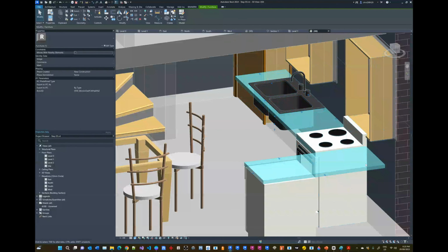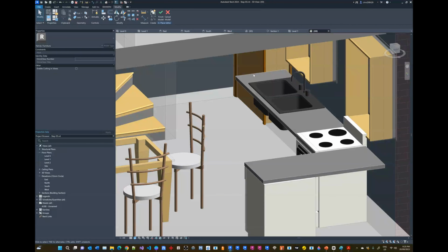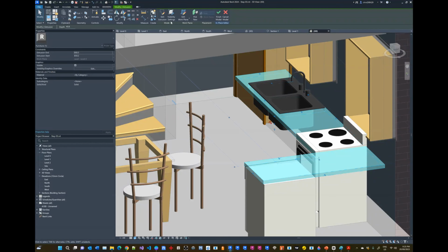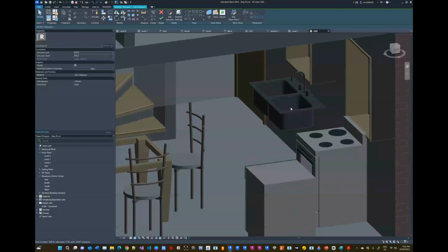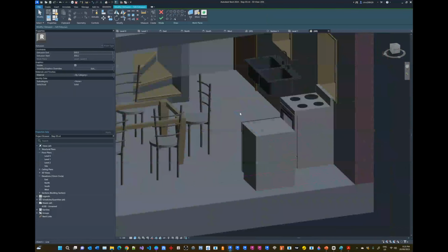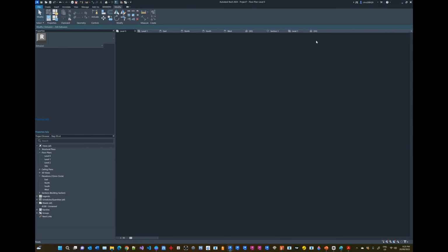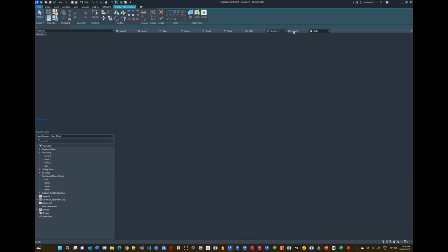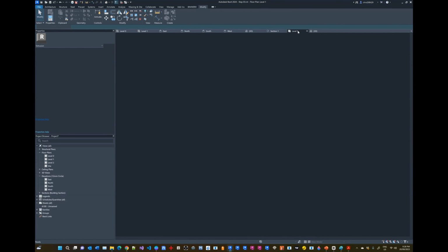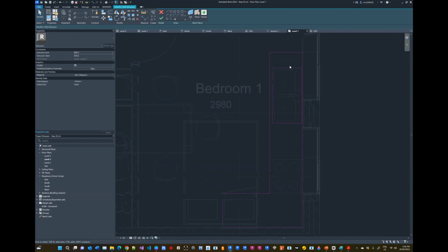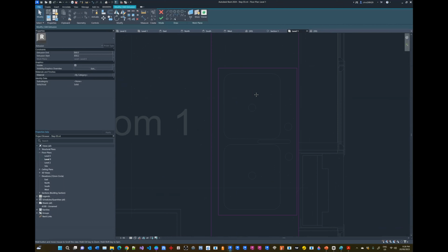So I created this external geometry around, and then if I click here on edit in place, and I select this void and I choose edit the extrusion, you can see that I created the external lines, and then where that sink sits on this level here, I keep selecting the wrong thing. I just made sure that I created another internal closed loop to create that sketch.